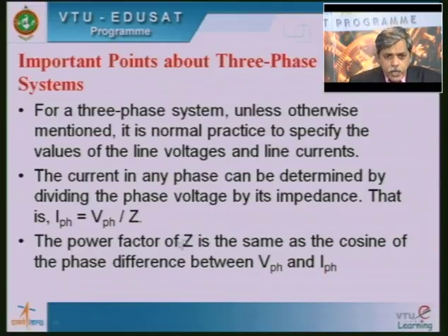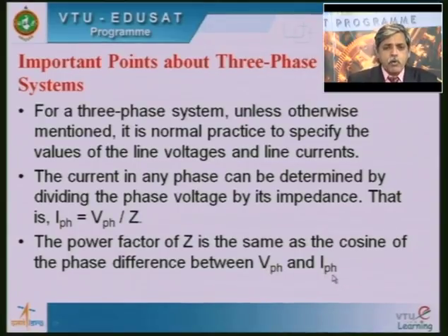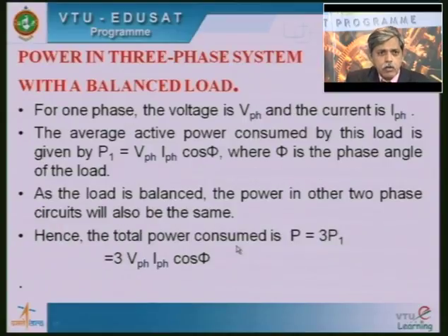Now, in calculating the power factor of a three phase system, we consider the angle between phase voltage and phase current. We do not bother about the angle between line voltage and line current; we always take the angle between phase voltage and phase current in calculating the power factor. These points you need to remember for all the three phase circuits, this is very important.